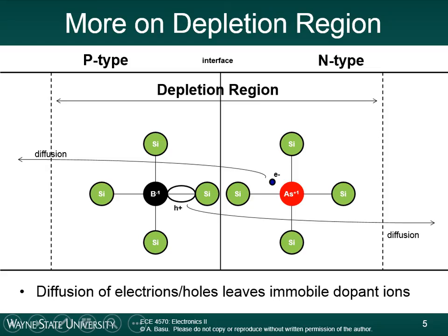Assume the doping density on this side is less; the spacing between these black circles, or negative ions, is going to be more. So in order to maintain space-charge neutrality, the length of the depletion region on this side would have to be larger than the length of the depletion region on this side.